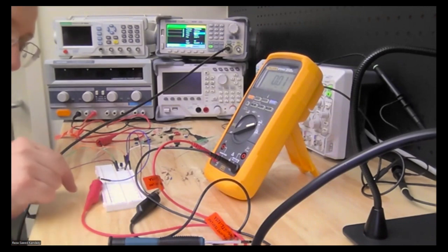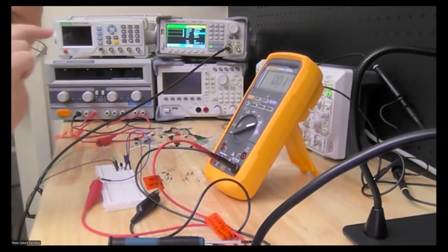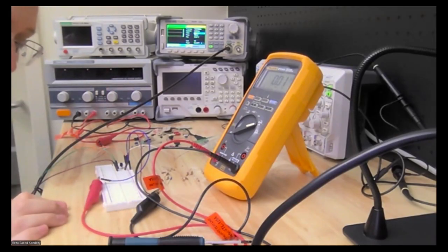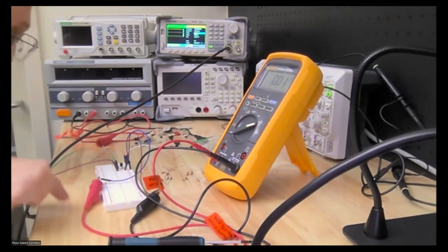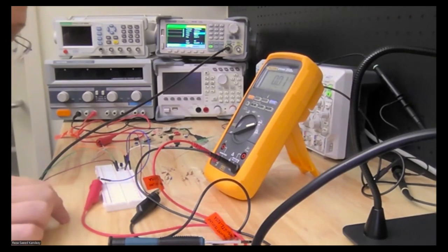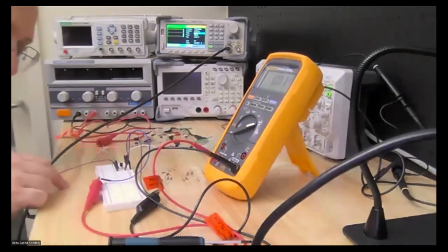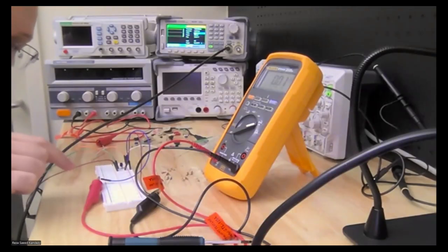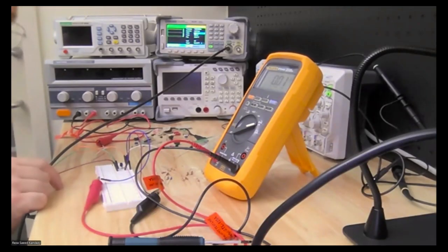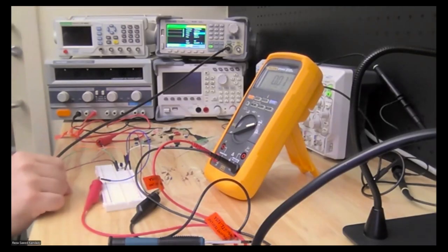So you can calculate on paper the difference between the measured voltage of gate and source minus the threshold, which is 2 volt, okay? And you already have the current measured with your multimeter. So if you divide the square of that difference by the current that you measure, you have the Kn coefficient for this specific transistor.